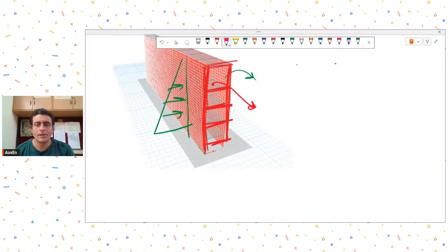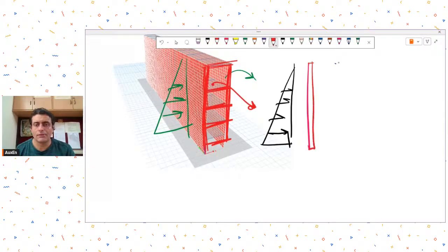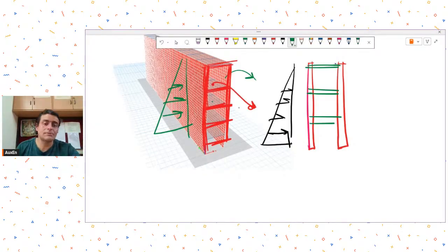What I mean is, in elevation, let's say this is your retaining portion. This is your retaining wall on which there is a soil fill acting. Now you make a vertical column over here, at whatever distance it is allowed, and then have a stiff beam attached to it. So instead of having a slab, which won't help you as much, a stiff beam element will help you, and it will just become a frame subjected to lateral loads, isn't it?